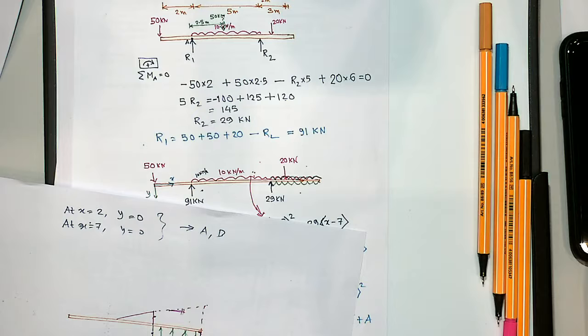I have a question about your course. We have decided to choose this when your lift is equal to weight, so it's kind of an equilibrium. But are we allowed, because we found the centre of gravity in your weight effect, to just treat the weight as a point load at the centre of gravity? That's for calculating the equilibrium. But when you calculate the bending moment and things, then you have to consider it as a UDL. But it doesn't act as an actual centre.